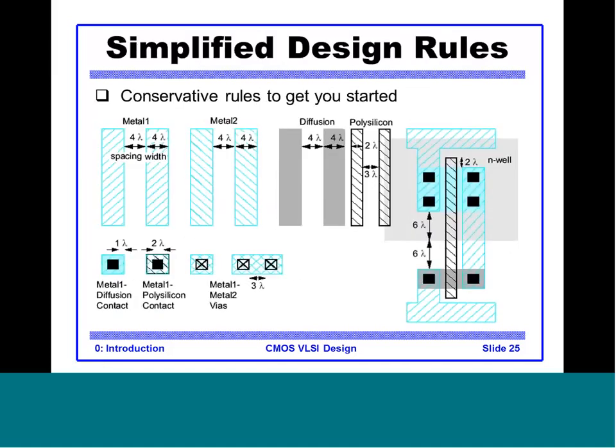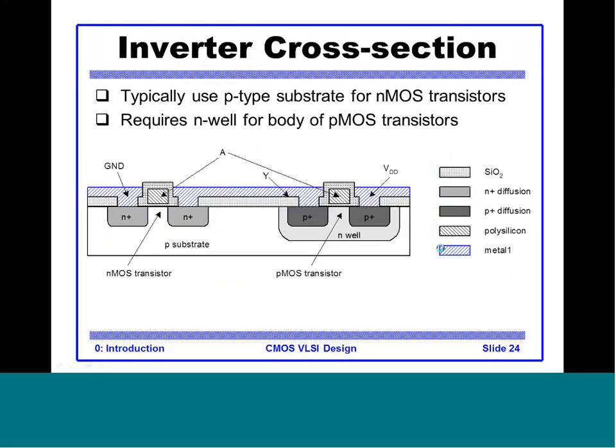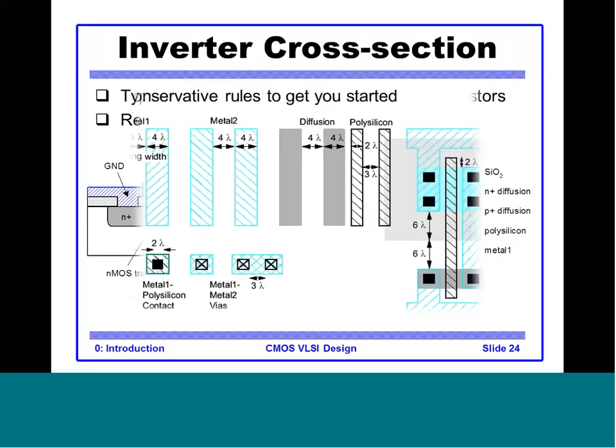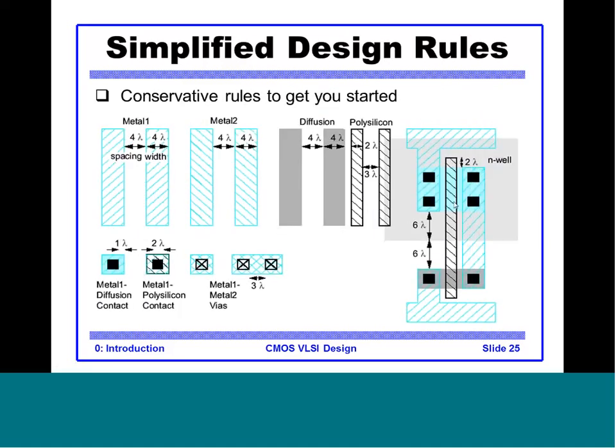Now this we'll see when we see the stick. We will not see much of design rules in this course. The design rules are very specific to technology and very specific to the kind of layout. So the picture here represents the inverter layout. This is the cross section, the side view, and this is the top view of the layout.